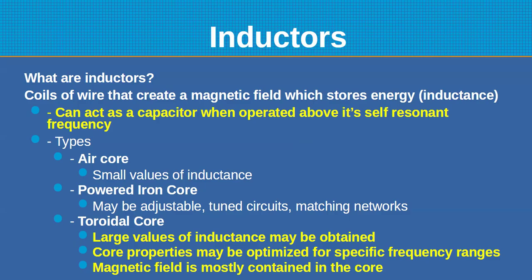The same thing happens with capacitors. As you approach the resonant frequency of a capacitor, because they'll have some inductance, they start to look like inductors at frequencies above their self-resonance. That's one of the things you have to take into account if you're designing circuits, of where those self-resonant points may be. So you don't want them to be where you'll be operating.